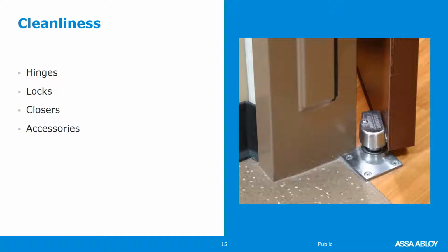Automatic operators, mount them on the outside of operating rooms or other clean type rooms so that you don't have dust gathering on the top of the power operator. Antimicrobial finish on hardware helps cut down on bacteria and the spread of bacteria. It doesn't allow it to live on the surfaces. And wave buttons for power operators. Instead of touching the button, just hold your hand close, and that way it helps with the cleanliness as well.